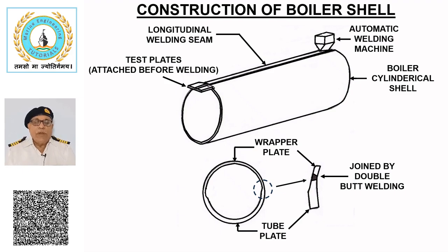Annealing involves heating the material slowly in a furnace to approximately 600 to 650 degrees Celsius, below the critical temperature of 723 degrees Celsius, above which phase transformation occurs. The material is held at this temperature for 1 to 2 hours and then allowed to cool down slowly. The cooling rate is determined by the desired material properties.